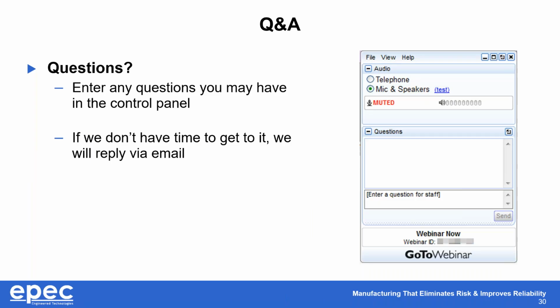But generally, since we can't supply boards with that material, it circles back to us evaluating the designs and seeing, okay, does the design truly need LCP? Can we deviate to just standard polyimide? And sometimes the answer is yes. Sometimes material considerations are too strict and you end up finding that standard polyimide works just as well as LCP, and that you don't need to spec out an expensive exotic material just to have your design function. Sometimes it'll just function normally with polyimide.